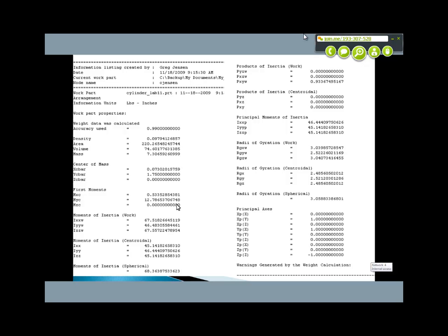In real life, you can't ever make anything as accurate as what the CAD system predicts. And so what they typically do is once they get a stage built, they do the exact same thing that the tire shop does. They spin the rotor along with all the blades on it, and they figure out the out of balance, and they add weight or remove weight to try and bring that disc into balance so that it doesn't have any of the wobble or vibrations that it would introduce.